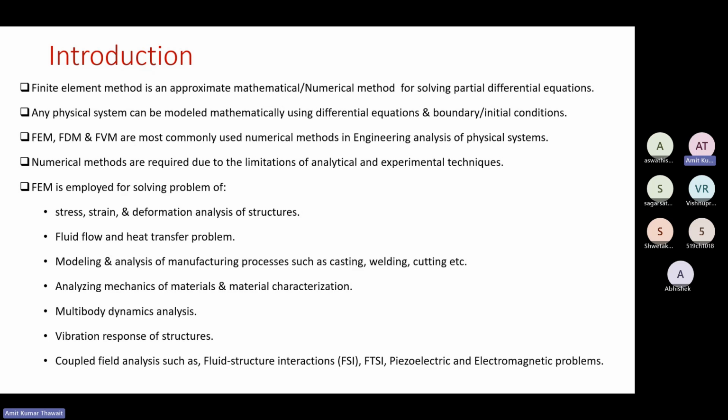We can characterize materials also. For any material we generally use the tensile test, compression test, torsion test, some fundamental tests for getting its properties for different loading conditions. Those virtual experiments we can perform using FEM, and we can characterize any material.